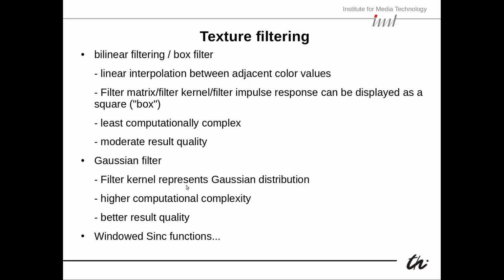Okay. Here we have a higher computation complexity because this function is more complex, but it results in a better quality. Then we could also take sinc functions, for instance. So remember, a sinc function is simply the impulse response of an ideal low-pass filter, but the sinc function is even more complex.